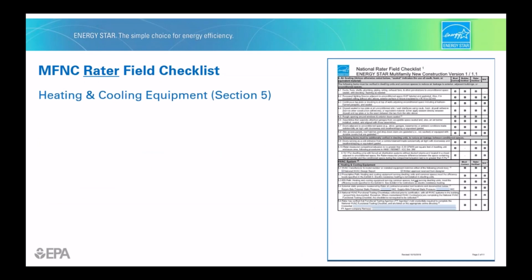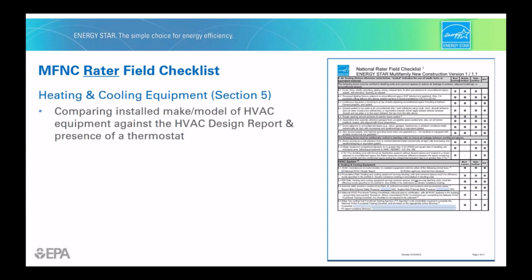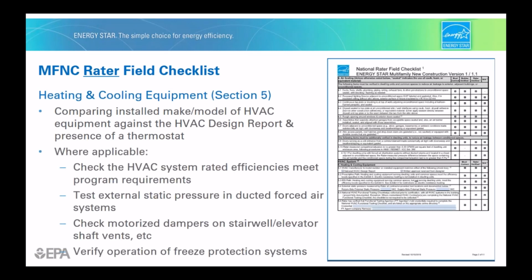During construction, the rater is also responsible for conducting site visits to verify the presence of the mandatory items in the rater field checklist. The ones related to HVAC systems are in Section 5 of this checklist and include inspections to verify that the installed equipment matches what was specified in the design, that thermostats are installed in the dwelling units, and a variety of items that may not be applicable to each project,